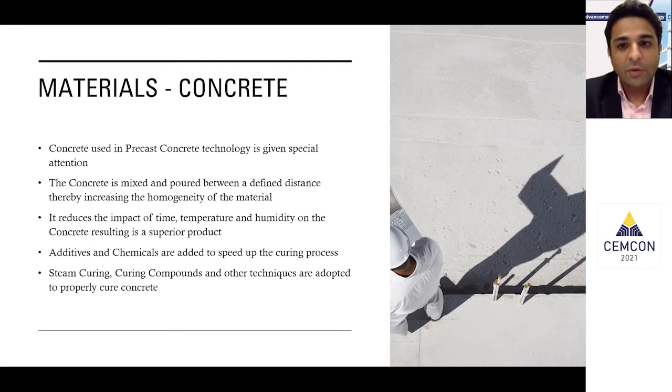understanding of that. Furthermore, because our concrete is manufactured, we have more flexibility to try out different things, to try out newer materials, and to incorporate materials that will increase the life of our concrete. In the curing part, we use things like curing compounds, steam curing, and other curing technologies, which can again ensure that our concrete gets the attention it needs to perform to the best of its abilities.